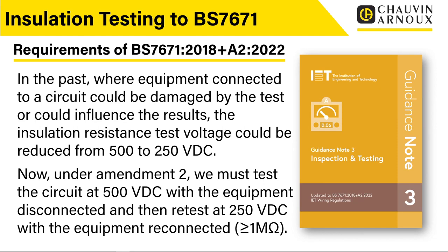So I think they're now trying to put the emphasis and say, look, you need to make the effort to test at 500 volts. And the reason we're doing 500 volts is because it is above the supply voltage. You know, we are putting this insulation under some stress. So again, I think in principle, we should carry out these 500 volts tests. However, I do foresee, particularly with electrical installation condition reports on existing installations, that it may be difficult to actually do this 100% as per the letter of the regulations there.